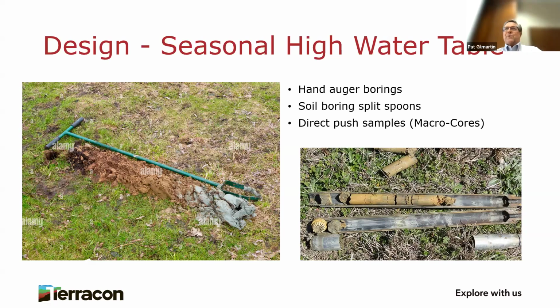And sometimes you get driller refusal rather than material refusal, but it's pretty hard to do a hand auger more than 10 feet deep. This is common in the Triassic Basin and parts of the Piedmont, where we'll send our soil scientist out with a drill rig to look at the soil samples that come up from the split spoon samples.